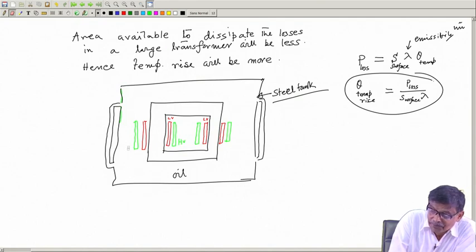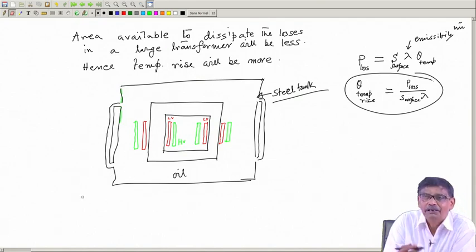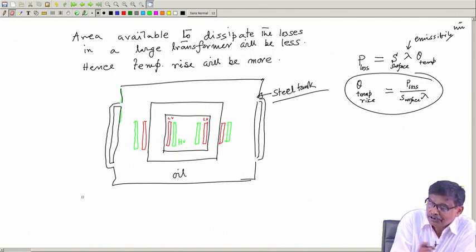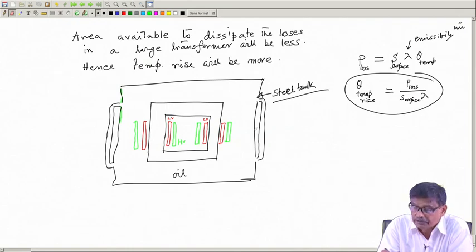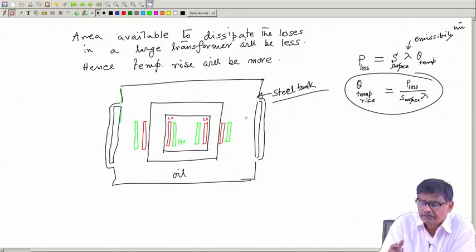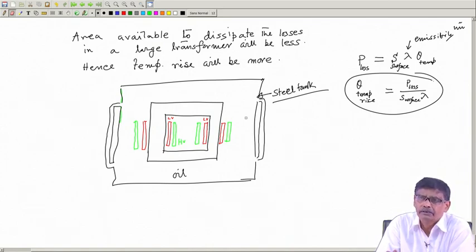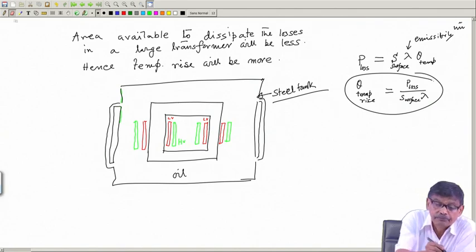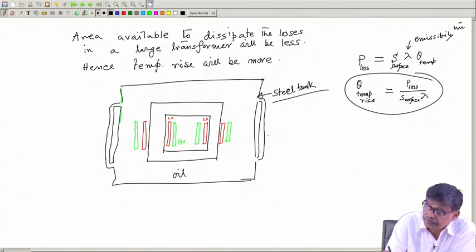So, oil will go up and it will have also natural convective currents, it will improve the cooling. So, heat will be coming to the cooling tubes. Mind you, it is not only one, it is just one I am seeing. Behind this, along all the surfaces you can connect. On the top surface and bottom surface, of course, no heat is assumed to be dissipated, because so many fittings will be there on the top. So, these are cooling tubes, cooling tubes.